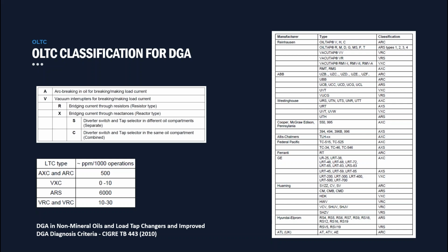Okay, the next one is from Alf: once sulfur has been found and the oil has been treated, does the continued presence of sulfides mean that the transformer is to be taken out of service? Also, is there some experience on how long a transformer lasts in terms of years once the sulfides are present? No, we don't have that information in terms of how long it will last.